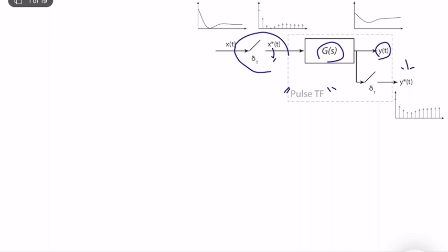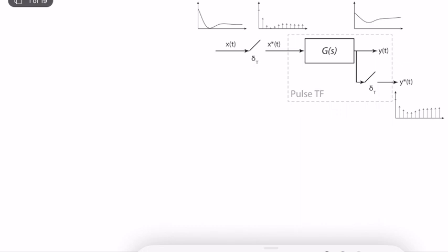The pulse transfer function is nothing but a discretization of a digital control system. We try to transform everything into the discrete time domain, and when doing that, we heavily use the concept of the star signal, which is an abstraction of the sampling, and the star Laplace transform.